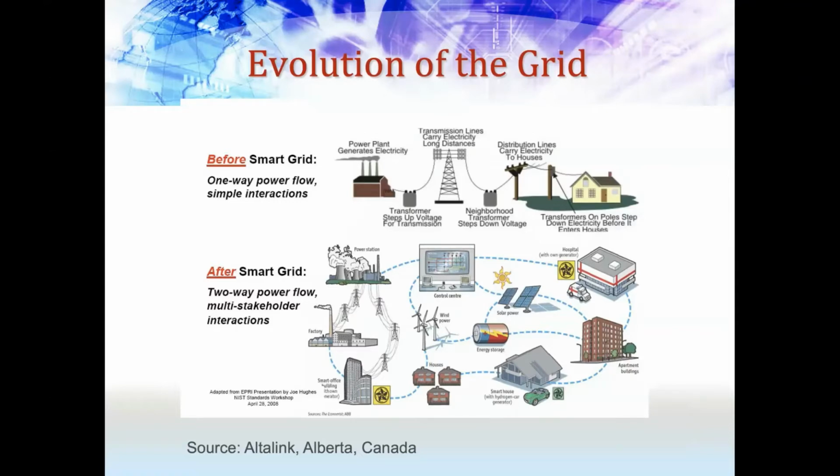Before smart grid, power was one-way flow, meaning it starts at the generator, goes to a step-up transformer, then it goes to the high voltage transmission line, power comes close to your load center, voltage is dropped down to a lower number, then goes to local neighborhood, your street, your building, your company, all of that. That's the standard practice going on for more than 100 years now.